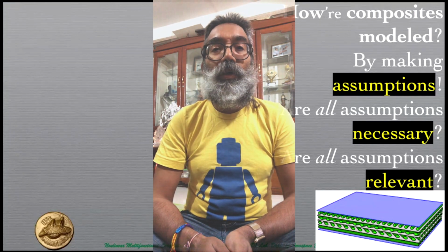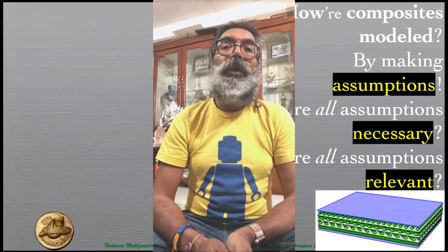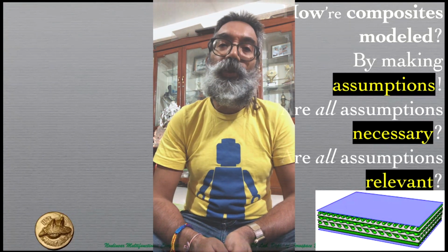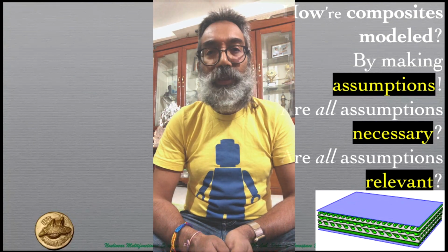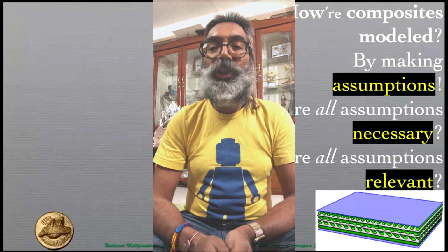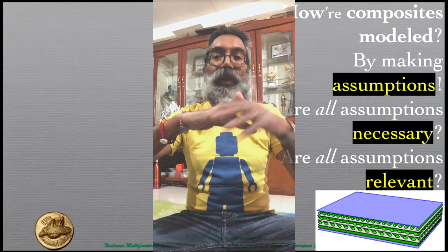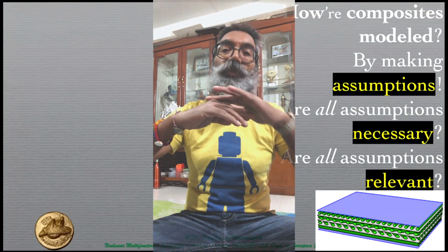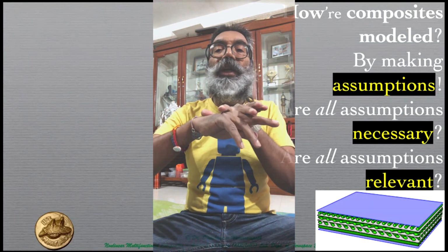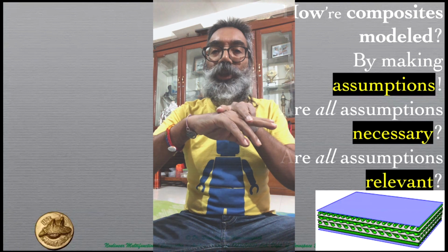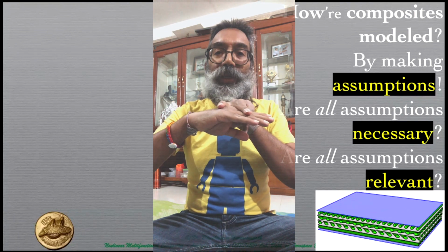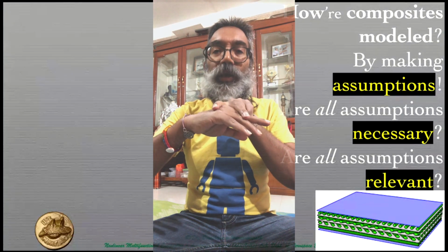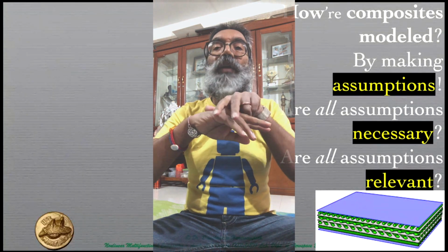Then you get on to two-dimensional problems, where you have one dimension, that is the thickness dimension, being dominated by the other two dimensions. So you end up with plates or shells, and therefore x1 and x2, which are along the surface of a shell, x1 in one direction, x2 in many cases chosen for convenience to be an orthogonal direction, but the only requirement actually is that those two directions should not be collinear or parallel to each other. That is basically all that is actually required. But you do have x1 and x2.